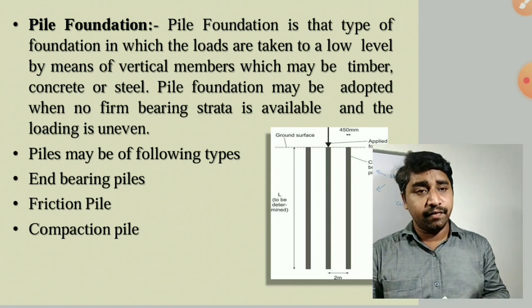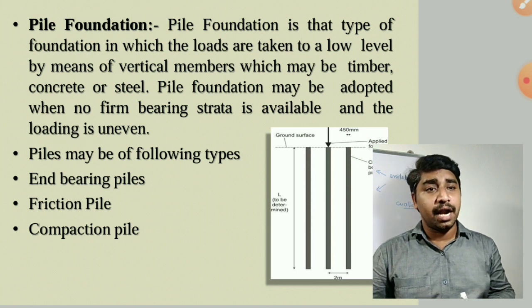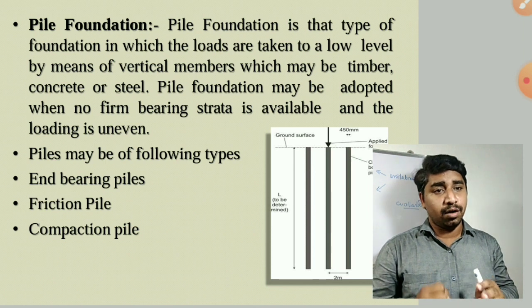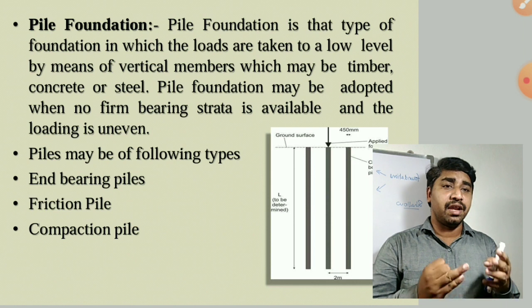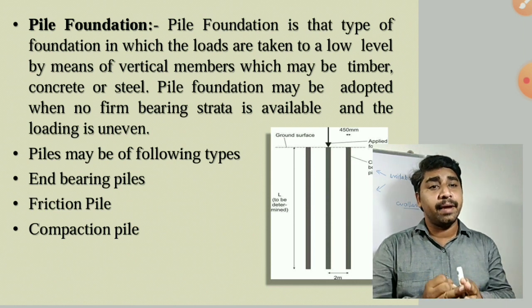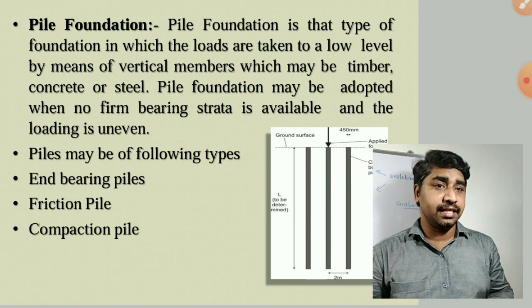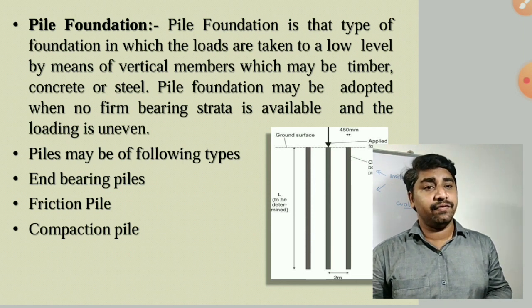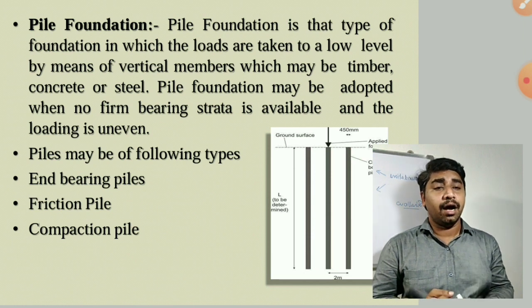Next, another one: a very weak strata or a very highly compressible strata is available at the ground surface or at a shallow depth. If the soil available is very weak, then also we'll be adopting deep foundations. So that is another case.